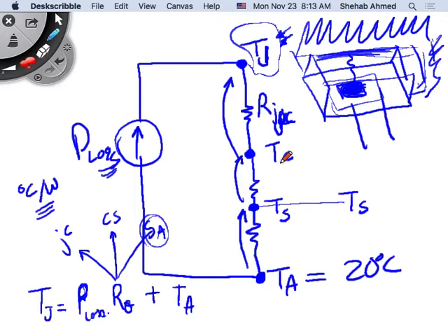So if you put a proper heat sink, if you size the heat sink properly, you will find that this resistance will typically be something in parallel, right? So if this is originally with no heatsink at all, this is a large number, right? If you just have the device hanging up in the air, like you see lots of boards would have the device there and there's no heatsink. It's an additional cost as well as size. So if you don't need it, you don't put it, right?